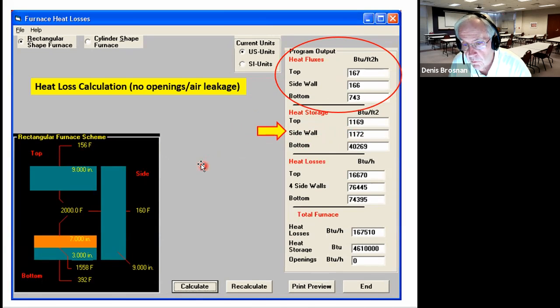And so for today's situation, it's doing the thermal conductivity calculation to get the values. It's showing you the outside shell temperature right here, the inside furnace temperature, and it shows you the interface temperature if there is an interface there in a multi-component lining. So it does pretty much the same thing, of course, as the thermal ceramics program. You can use it, but to my knowledge, you cannot change the data that's in the database. Whereas with thermal ceramics, you can add data if you want to. And so that's very useful for us.